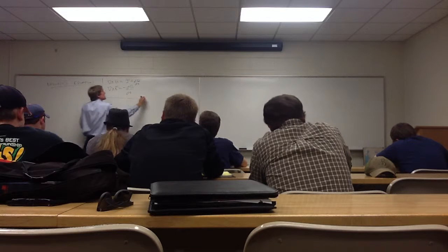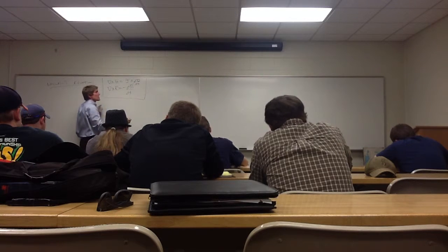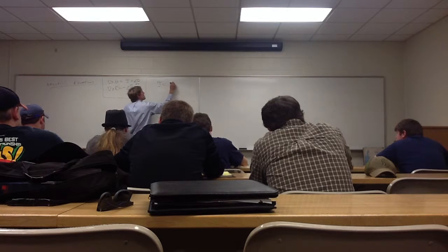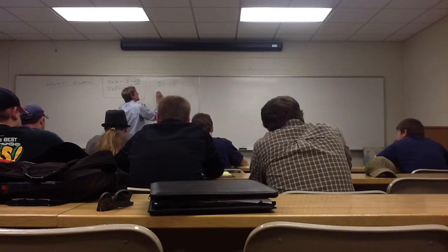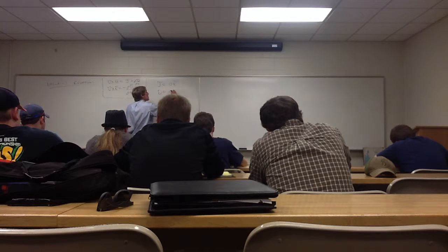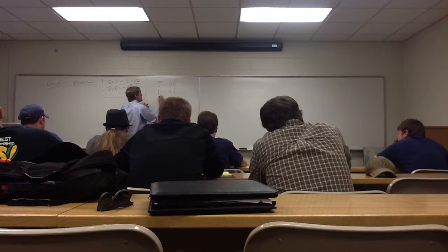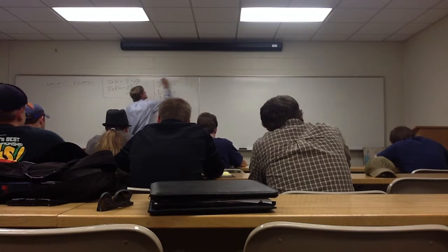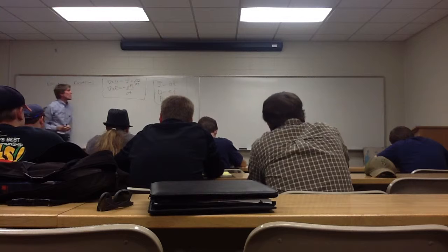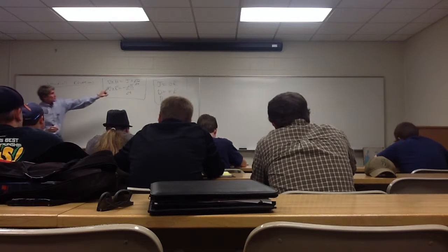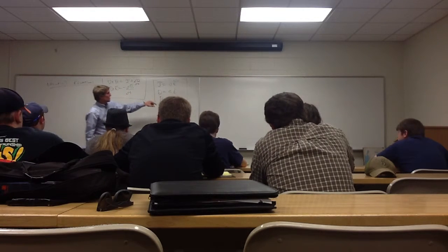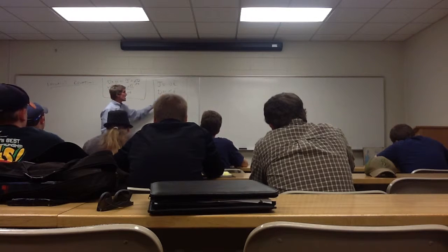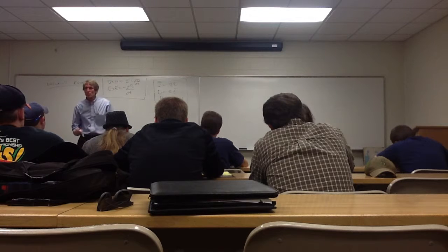I'm putting them up as high as I can. Here, there's some basic concepts you have to know. J is equal to sigma E. D is equal to epsilon E. B is equal to mu H. These are the equations that couple this. It couples the actual current density to the electric field strength with the conductivity, the D field from the E field with the permittivity, the B field from the H field with the permeability.